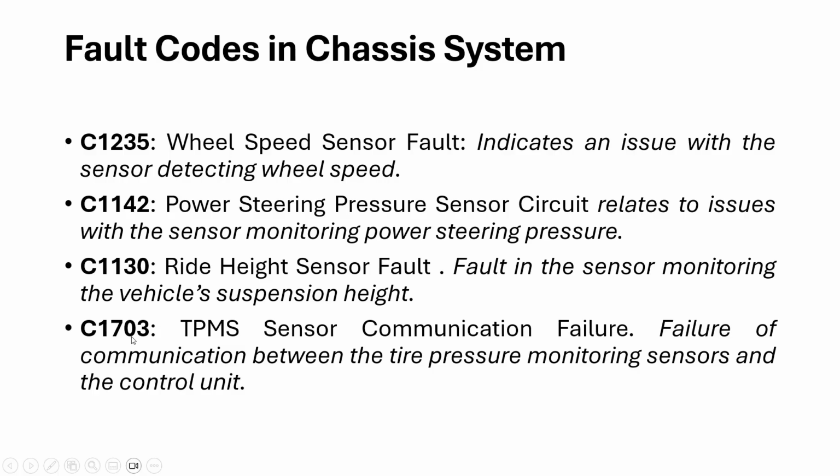C1703 is for TPMS sensor communication failure. It indicates a communication failure between the tire pressure monitoring sensor and the control unit.